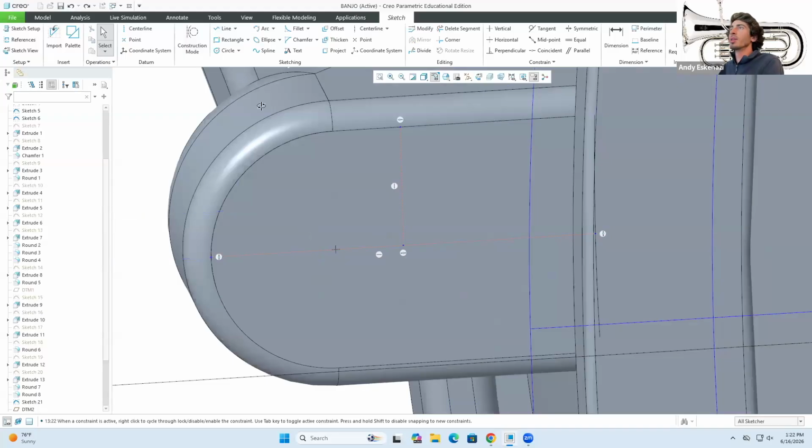Actually, honestly, the way to do it is draw circle construction, and suppose that's as big as the circle is gonna be. Then draw what would be a wedge, and that should be 60, and the angle between here and here has to be 60 as well. There we go. And we're gonna make these 2 construction, and then we'll draw a line that will go like that perfectly. Okay, good. So now we are gonna kind of repeat this pattern a few times.